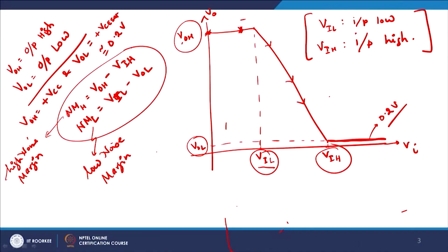We will discuss this also when we go to CMOS, but let us make it clear now as well. High noise margin means that, let us suppose you have a 1 being entered into the BJT, so my input is 1. Now suppose there is noise in the system. If the noise becomes very large, a 1 can be seen as a 0 by the input side, or it can change from 1 to 0. Suppose you had biased your device somewhere here, and your input cycle was slightly like this, no problem. The maximum value of the Q point goes from here to here, and your output is still high.